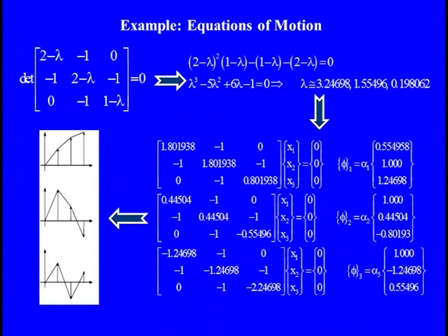While if we go to the other feature, the out-of-phase one, you can see that the first is 1. The first mass is absolutely on the top. The second mass is now going down exactly in the opposite direction, minus 1.2, and the third mass is again going on top. So, M1 and M2 are in an orthogonal position, and even M2 and M3 are along the orthogonal feature. Because of these different mode shapes at the critical locations, the stiffness is quite high and the exciting frequencies will be of more nature.